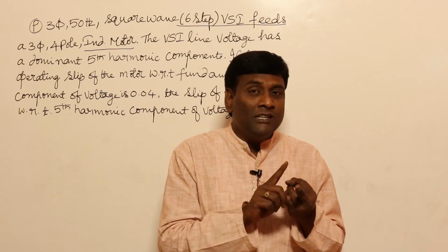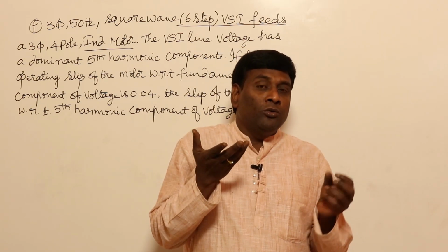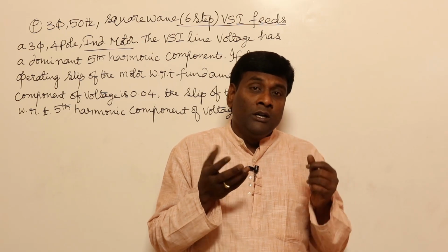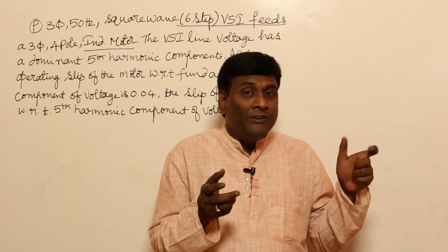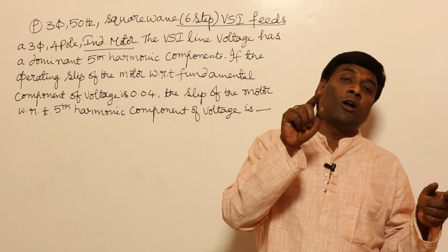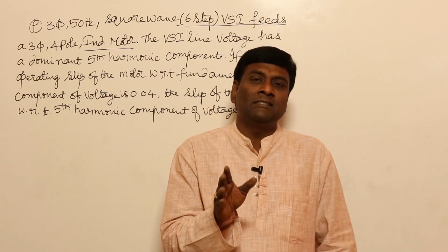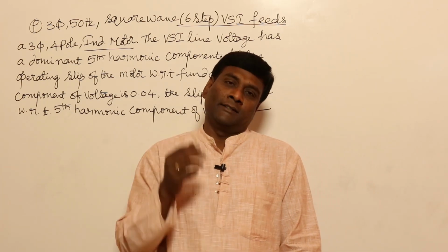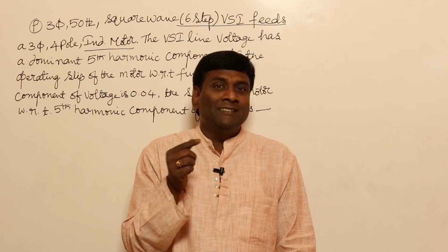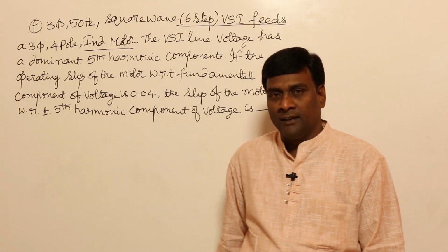So what will happen? Reactance offered is going to be increased. So if you keep on increasing the time harmonic component, reactance offered is increased, so impedance offered is increased, so the current flowing of that particular harmonic component will be reduced. Because of that, our textbooks say time harmonic can be neglected and they will consider space harmonic only. In space harmonic, the frequency will be the same. We will see it in the detailed analysis.